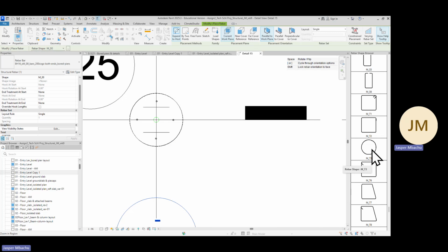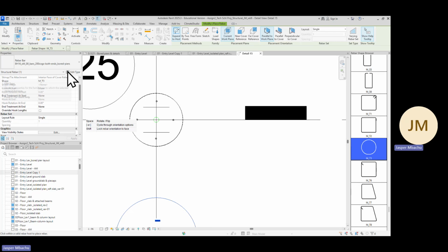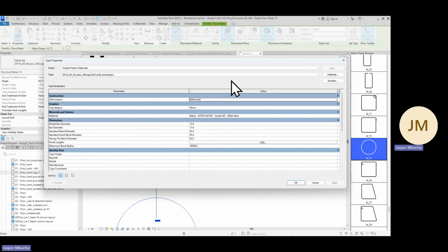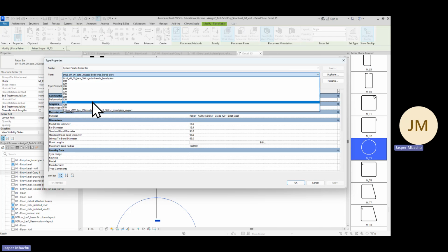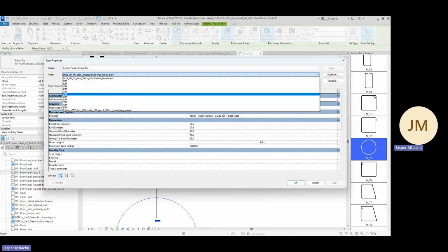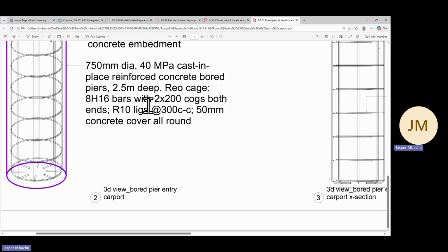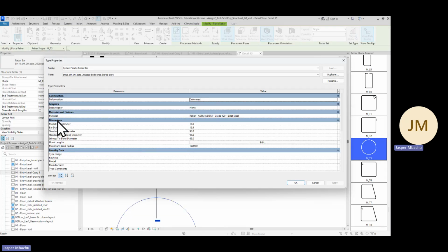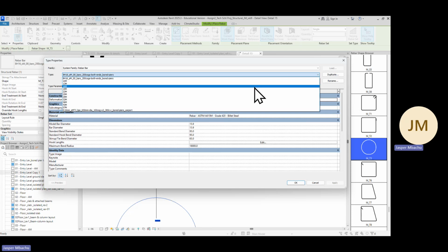All right. So everybody click on this shape, and just click on edit type, and you go to 10. Anyone that is 10 millimeter, because let's bring out our schedule and see what it was. It's R10. Okay, we'll come back to copy this to give it a designation. So we have to select 10 millimeter bar there. Under the type, pull down the type and select.